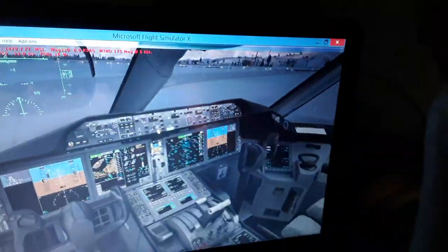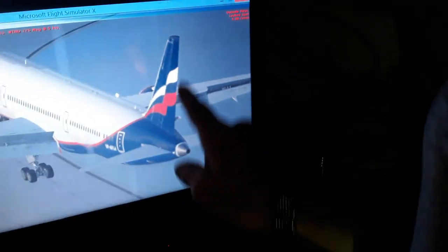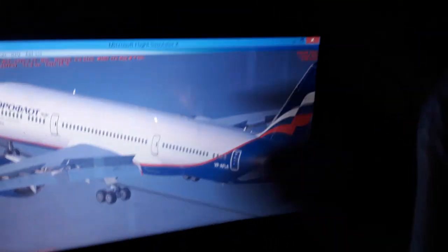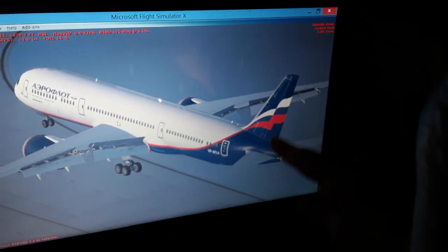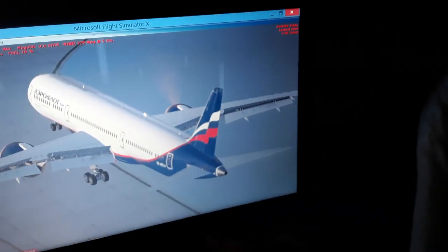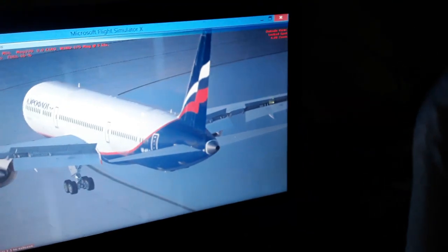When we are on the ground and steering the aircraft, we can use both the rudder here, as you can see, rudder control, left and right turns, and also the nose wheel together. So we'll talk to you about these things now. Also the elevator, climb and descent. Like this, you can see we can also trim the elevator or the whole stabilizer, depending on the aircraft.